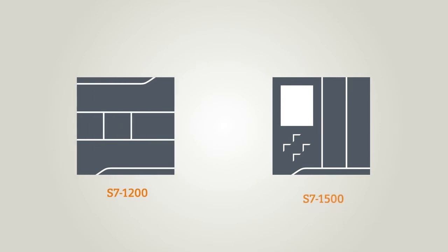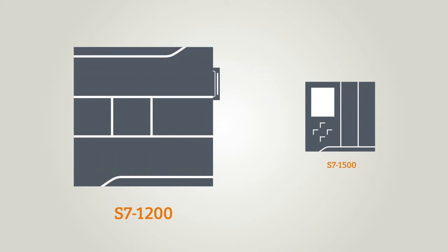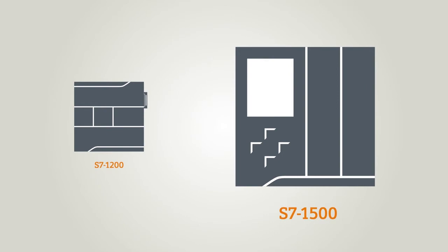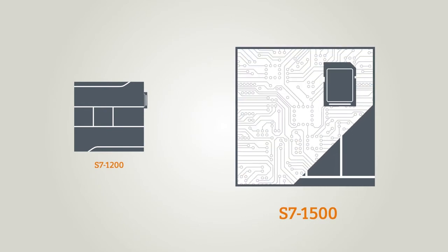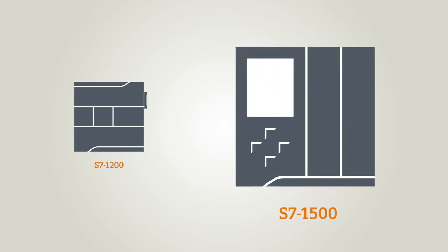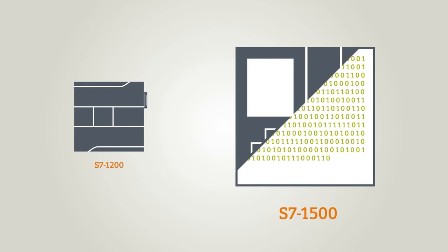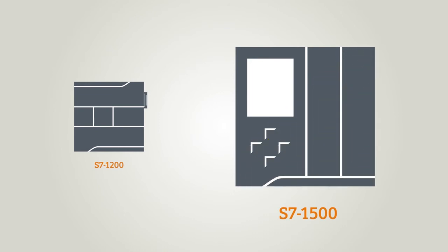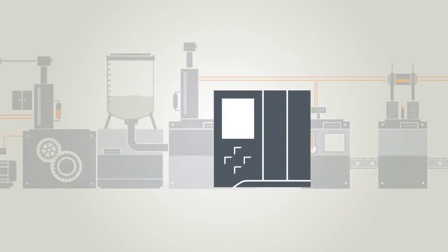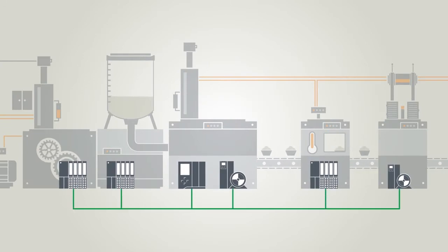The integrated load memory of the S7-1200 was designed for this. It can also be replaced with a higher capacity SIMATIC memory card if needed. The load memory for the S7-1500 is always located on a SIMATIC memory card. Once downloaded to the load memory, the firmware of the controller interprets the project data and then parameterizes the modules associated with the controller during startup.